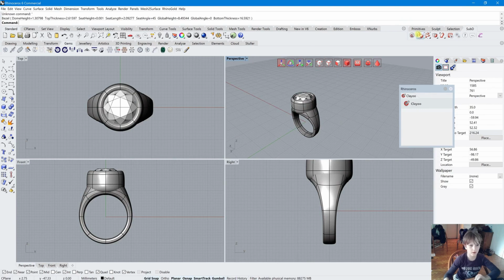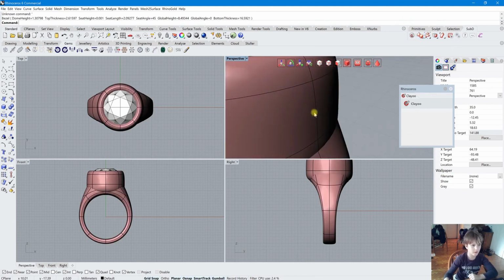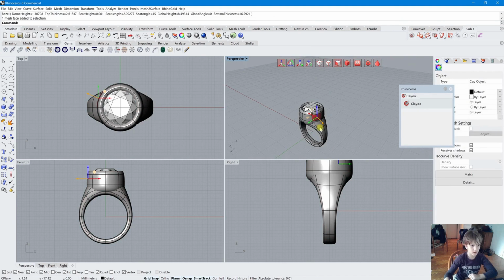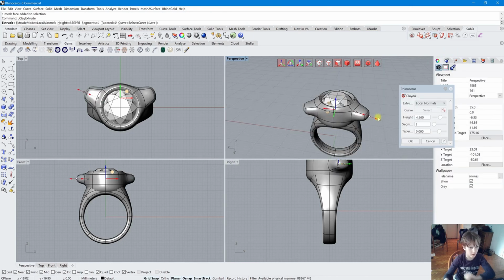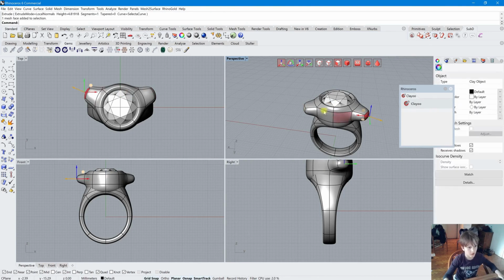Now that we're ready to edit our 3D model, let's start by selecting specific parts of the mesh. For example, we can choose these 2 polygons. Once selected, we can use the extrude function, which pulls out new geometry from the chosen polygons, making the shape more complex and adding depth. After extruding, you'll see that the polygons extend outward, creating new faces and giving the model more volume.